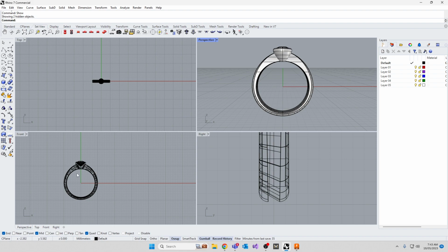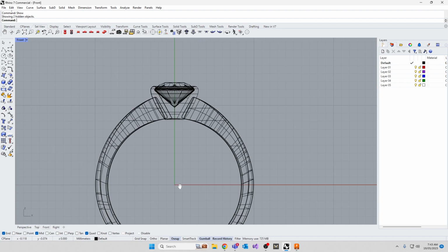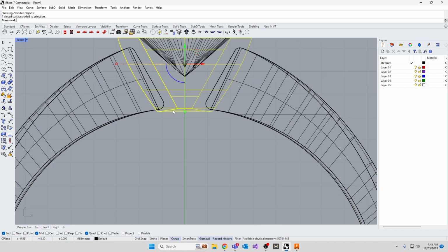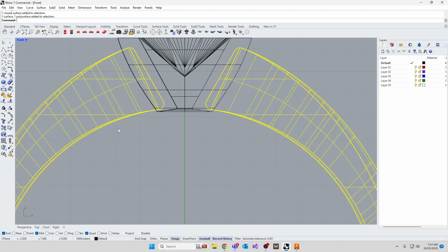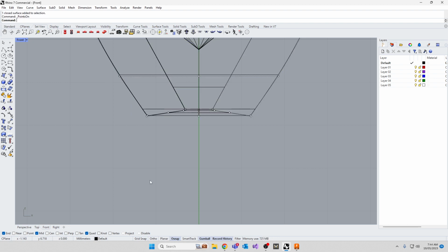So in our side view, we want to cut that off. So I'm going to introduce a new little command. It's kind of useful sometimes and kind of not useful sometimes. All right, I'm going to super select here. I'm going to hide you. Can I super select? Cannot. F10. Turn on the edit points. Grab view. I just want to pull them down.